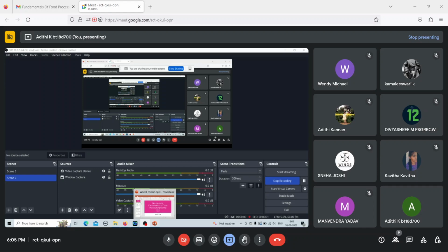We are not including steam here because it's a separate coil itself. There is no mixture of the feed and the steam. You are not mixing the feed. There is no direct contact of the feed and the steam. And whatever steam you are letting in, you are taking it out as well. So you are not including steam in the total mass balance. We are including all the other streams that come inside and go outside of the evaporator. Hope this is clear. The steam and the feed are not in contact, first thing.